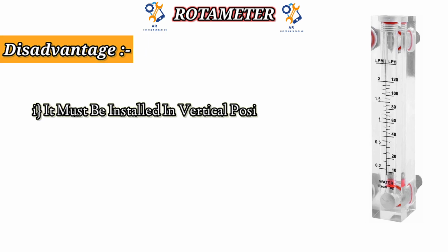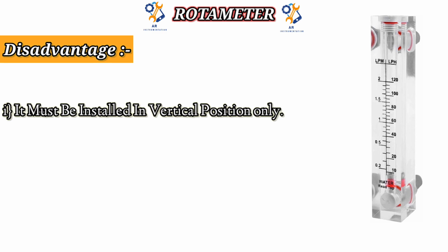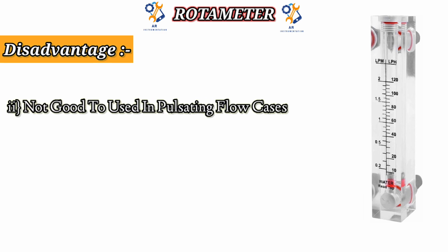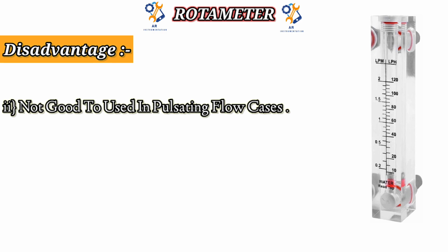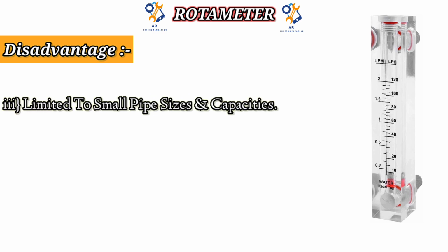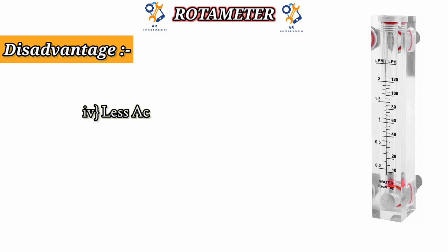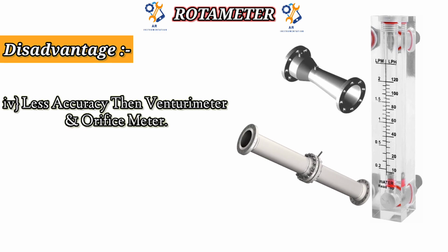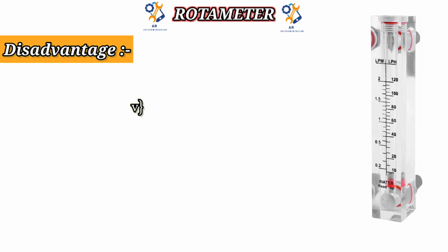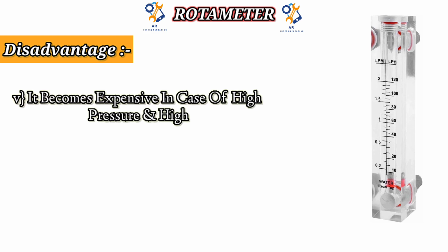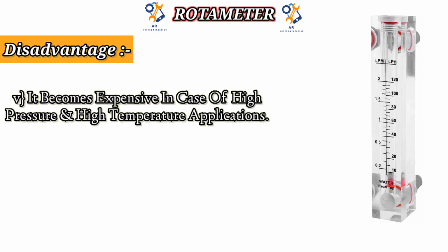It must be installed in a vertical position only. It is not good to use in pulsating flow cases. Limited to small pipe sizes and capacities. Less accuracy than a venturi meter and orifice meter. It becomes expensive in case of high pressure and high temperature applications.